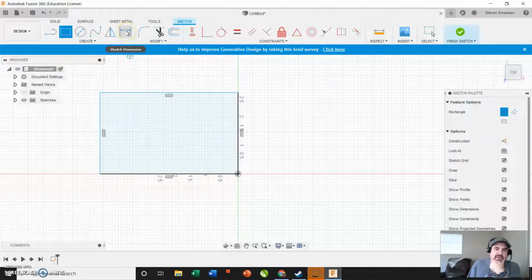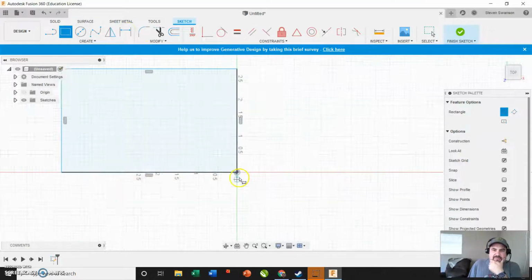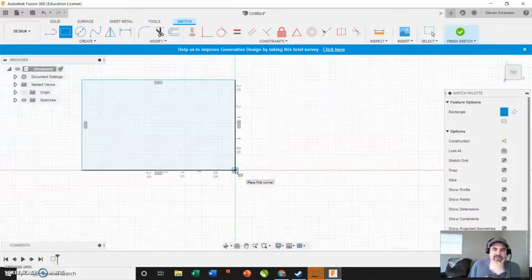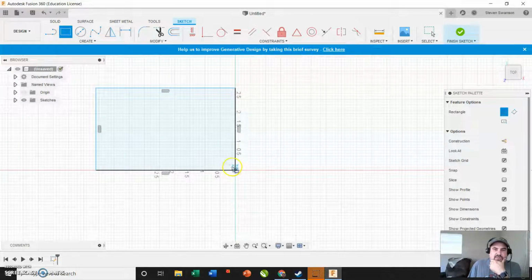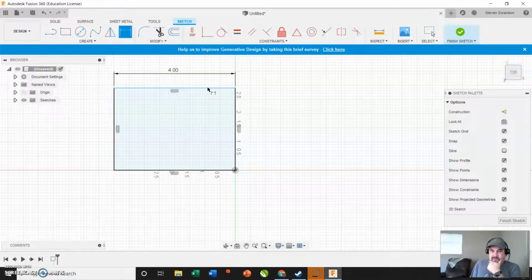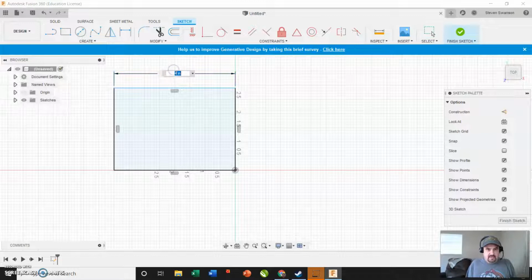For example, I think I already have a constraint by clicking this corner right here. When I started there, I've built in a constraint saying that this drawing always has to start here. Here's another constraint. I'm going to put one right here. I said that this has to be, let's say, 4 inches wide. Okay. I'm going to put another constraint right here. So, by the way, let's look at this right here. Do you guys see that D? Oops. If I move, it's going to go away.